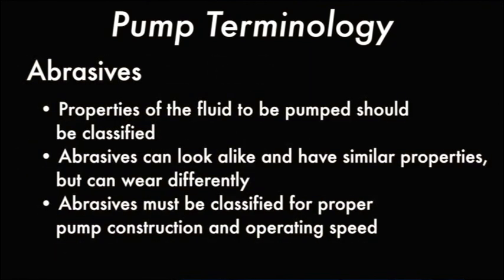The abrasive properties of the fluid to be pumped should be classified. Abrasives can look alike and appear to have similar properties. However, they can wear differently. You must classify the fluid in order to select the proper pump construction and operating speed.